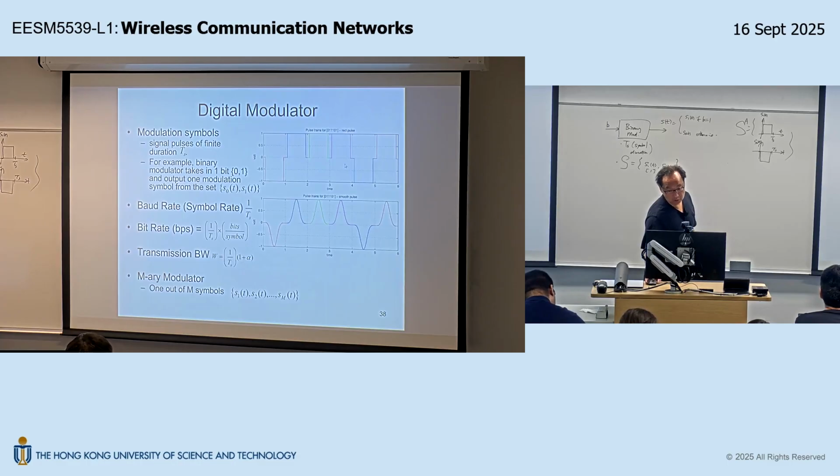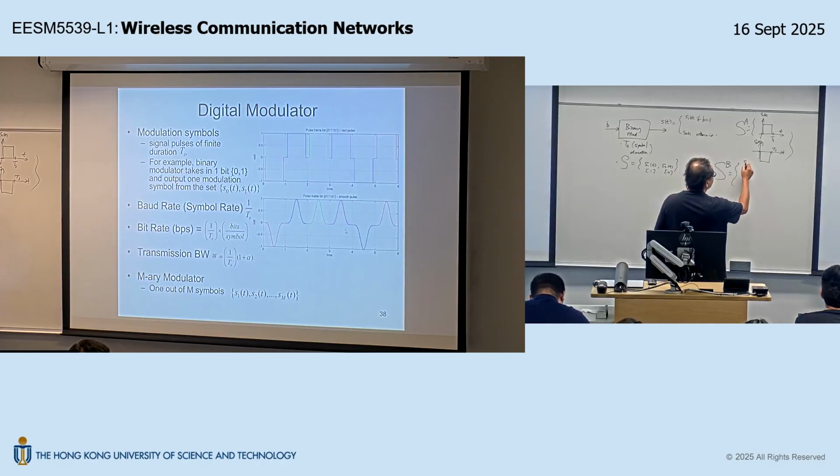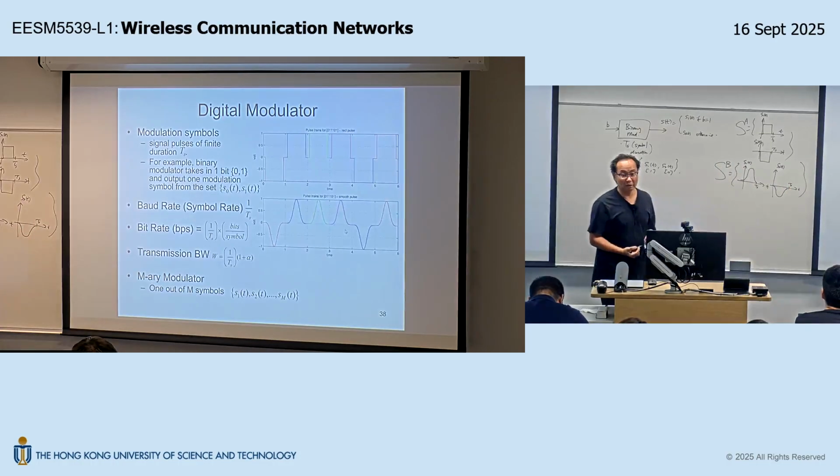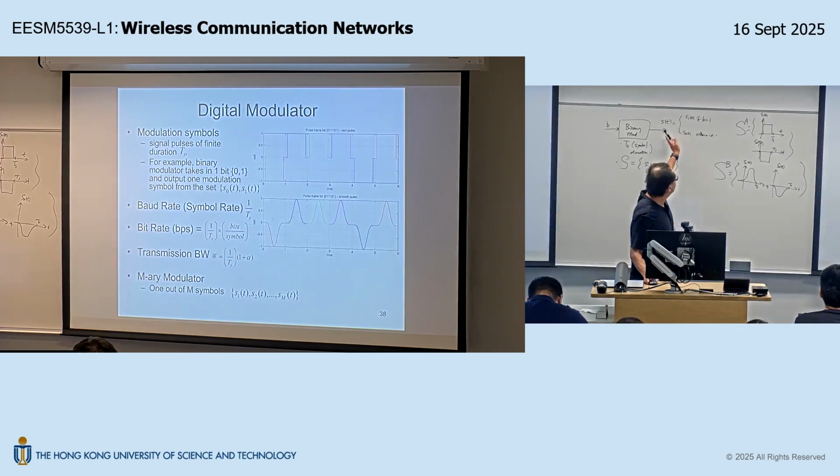Now, in the second, lower figure, is another design, design B, where my two waveforms will be given by smooth pulses. Okay, so that will be design B. So using design B for the same input bit sequence, 0, 1, 1, 1, 0, 1, the output waveform of the binary modulator would look like this second figure.